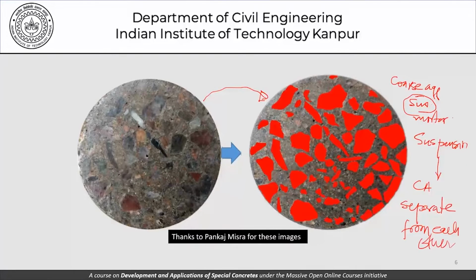This is not the type of material where the coarse aggregates are in contact with each other and there is a certain amount of void here which is filled with mortar. No, the coarse aggregates are suspended. They are separated from each other.